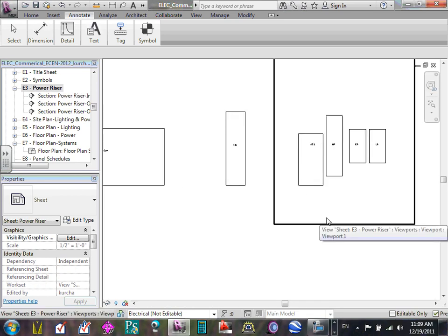Now, some of you will say, Chad, the names are so small. Can I make it bigger? No problem. We're going to go edit the type of the text and make the text bigger. But do me a favor, Phil. Every time you edit a component, get into the habit to duplicate it. What happened in the past, guys, the students will go edit the text, not knowing that the same type of text has been used elsewhere. So you try to make it bigger here, but it looks so ugly in another view because you're using the same text. Every time you edit something, duplicate.